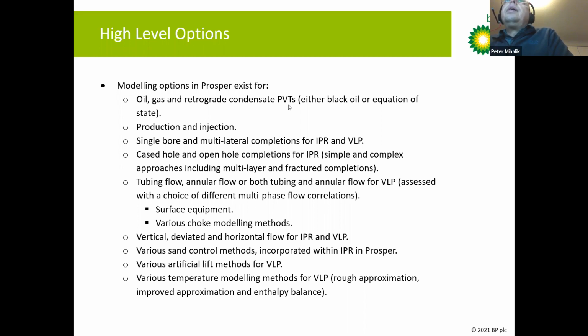Then we move on to what the well looks like, basically. It could be vertical, it could be deviated, you can even have horizontal flow. There are various sand control modeling options, which are basically incorporated within the IPR model. Loads of different artificial lift methods, and you also have the ability to control what kind of temperature modeling you want to do, either through first principles, via an enthalpy balance, or there's a so-called rough approximation method.